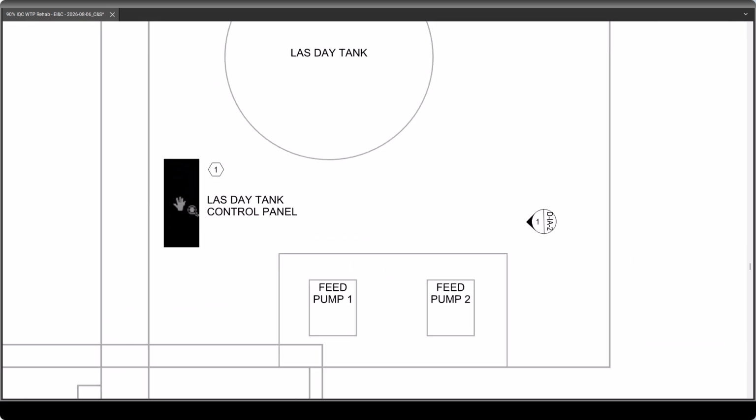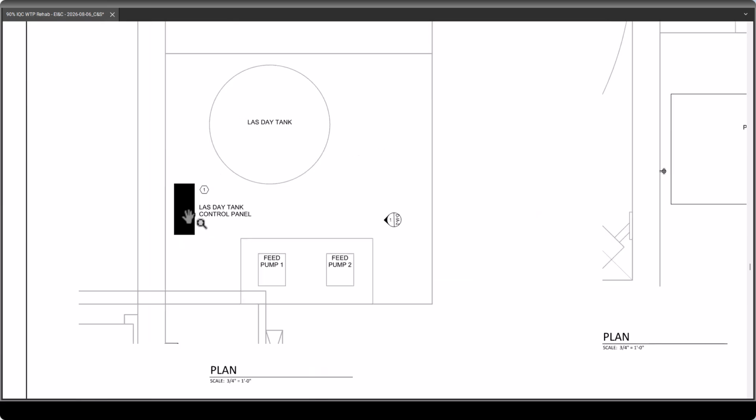Regarding the panel, I used an actual control panel family in my drawings, and you're welcome to go steal that if you want. It looks better, in my opinion. Like I knew immediately that this was a wipeout or a, whatever you called it, a field region. There we go. I knew immediately it was a field region. Does it get the point across? Yes, undoubtedly. For the most part, it gets the point across that there is a control panel. Done. Does it look better if you do an actual family? Well, yeah, because that's how Revit was made. In AutoCAD, that's a whole different story. We're talking about Revit. Any additional questions? Those are good ones.